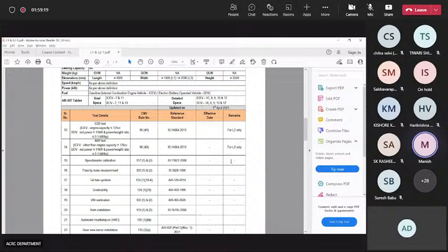So now you can see all the headlamps are on during daylight condition, either the headlamp is on or the daytime running light is on. If your vehicle doesn't have a daytime running lamp, then your headlamp has to be always on, whether it's high beam or low beam. That is a regulation requirement that has to be met.